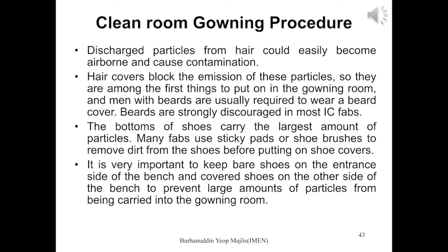The bottom of shoes carries the largest amount of particles. So many fabs use sticky mats or shoe brushes to remove dirt from the shoes before putting on the shoe covers. It is very important to keep bare shoes on the entrance side of the bench and covered shoes on the other side of the bench to prevent a large amount of particles from being carried into the gowning area.